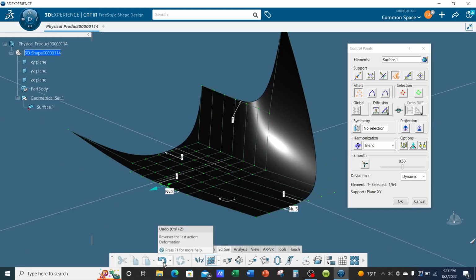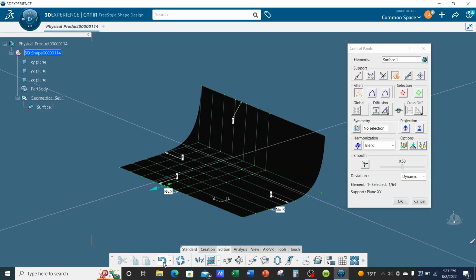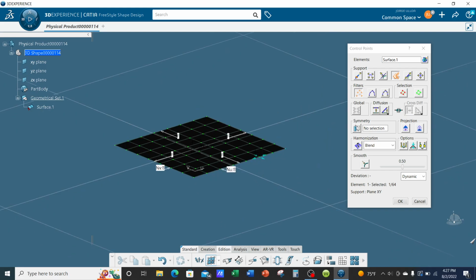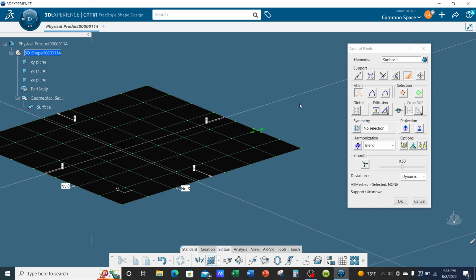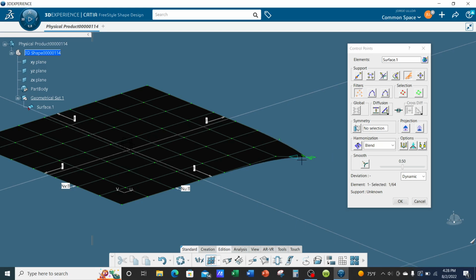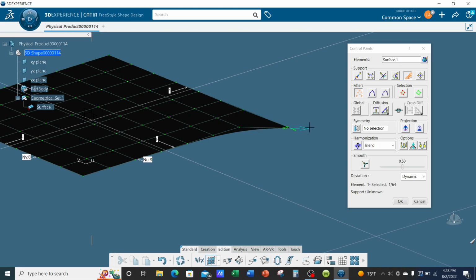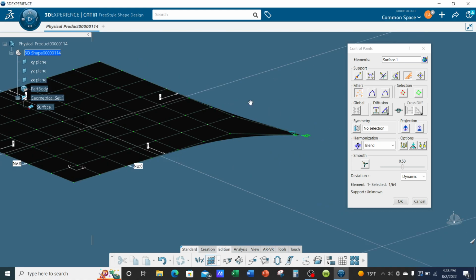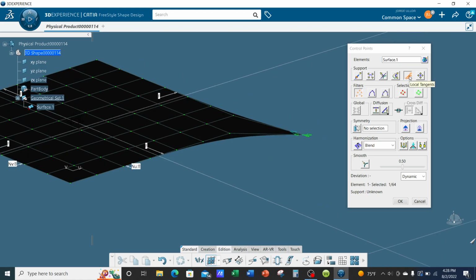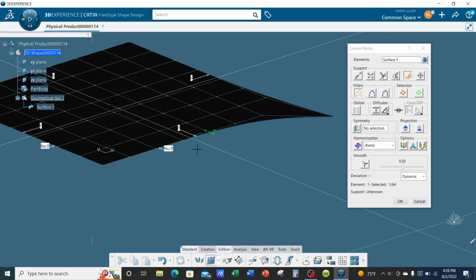All right, so let me hit undo a few times. All right, the next one will pull tangent to the surface. So if I click on that one, let me go to points only, deselect any possible points I have selected. So deselected all the points, and I'm going to pull normal to the surface. And it's also following the wire mesh. Let me go back to, sorry, I meant to say tangent. So I've been saying normal, I meant to say tangent. So this is tangent to the surface.